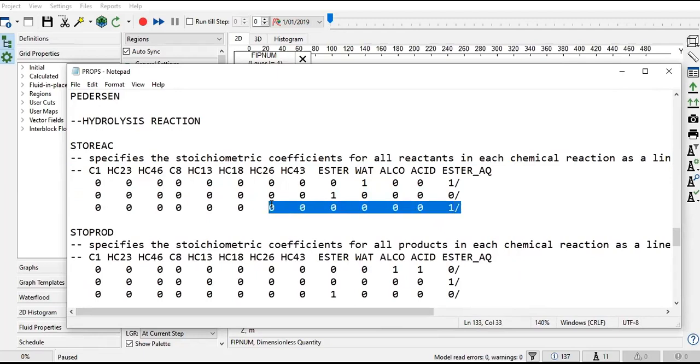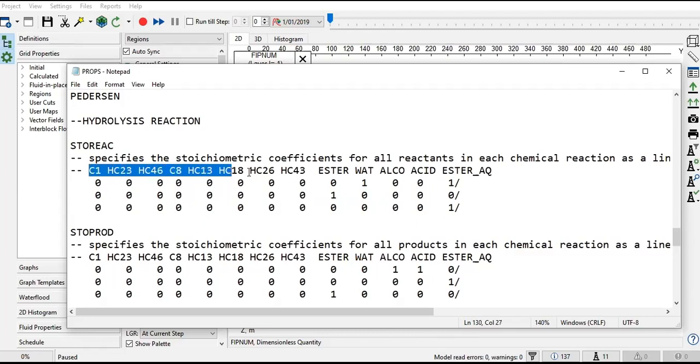And so we will set the hydrocarbon first. So that's why we will have 1, 2, 3, 4, 5, 6, 7, 8. Sorry, 1, 2, 3, 4, 5, 6, 7, 8, 9. First 9 of the hydrocarbon components, and then continued with the 4 water components. So 0 means that they will not be involved in the reaction, and 1 or any positive number, they will be involved in the reaction for the 3 sets of reaction.